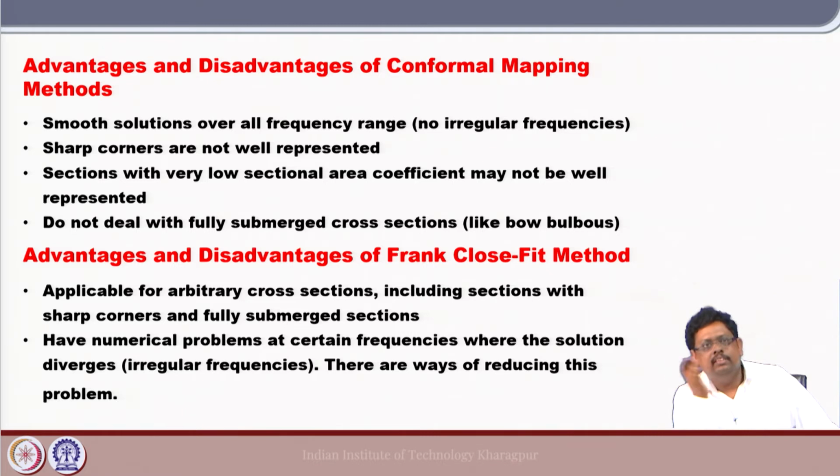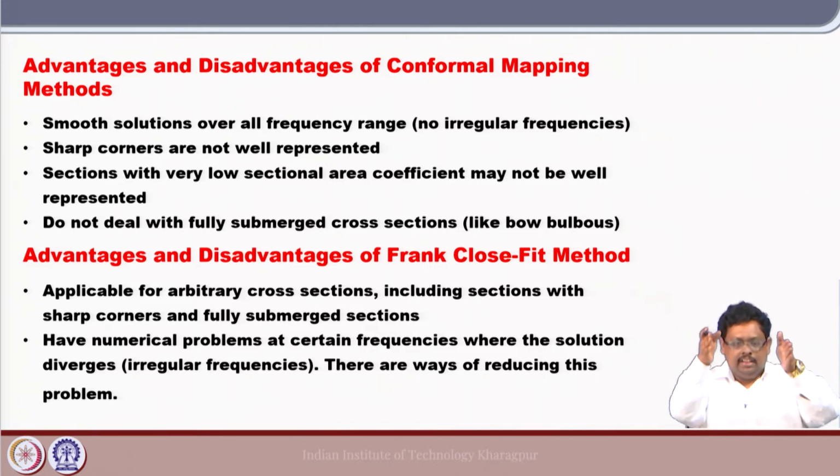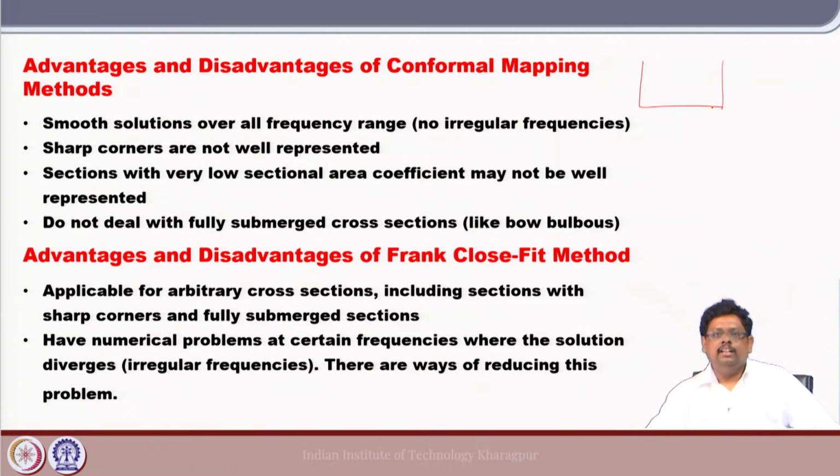So, it gives smooth solutions over the whole frequency range with conformal mapping. We do not have any irregular frequencies there. Now, sharp corners: you cannot get them very well. If you take a rectangular barge section exactly, it is very difficult to get using this conformal mapping.